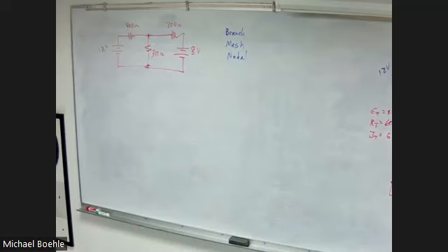Kirchhoff's voltage law. If I didn't know the polarity of something and I guessed, what happens if I guess wrong? Got a negative result. That's it. That's all there is to it. So you don't have to know. Like when I do mesh analysis, I always just draw my currents clockwise. It's just the way I do it. And the answer will all work out in the end.